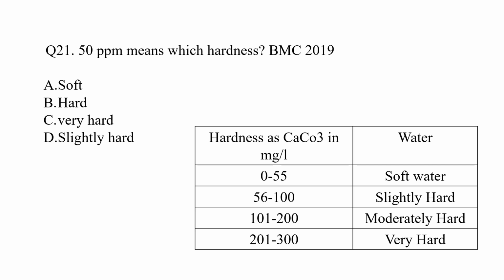Again, repeat: 0 to 55 soft water, 56 to 100 slightly hard, 101 to 200 moderately hard, and 201 to 300 very hard. This is a very important chart, remember this. So the answer is soft. Option A is correct.